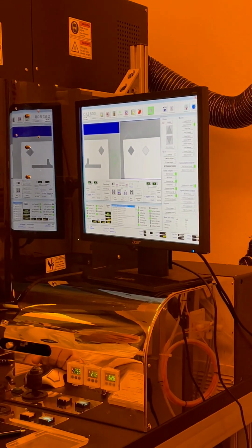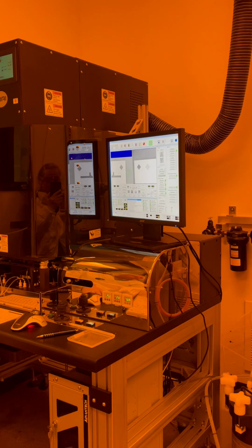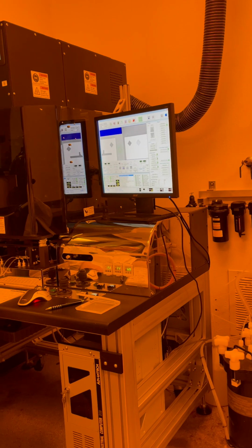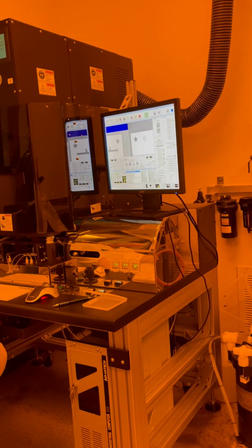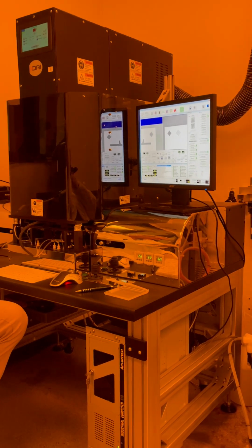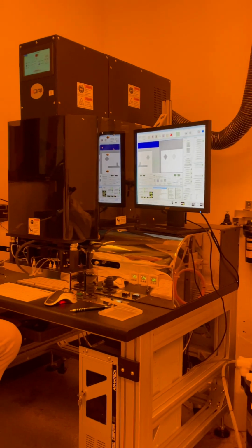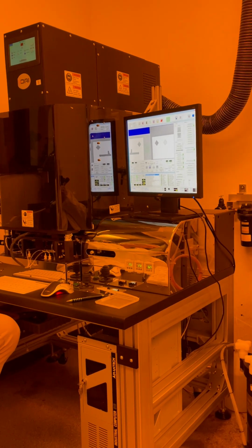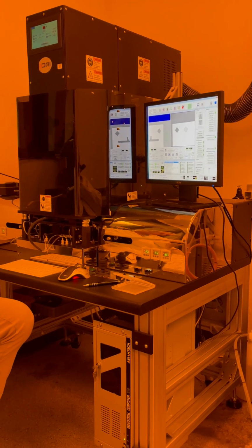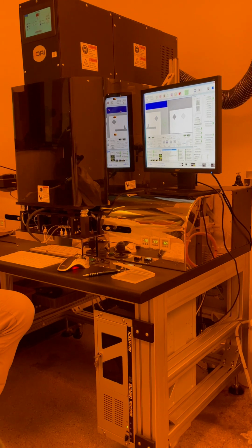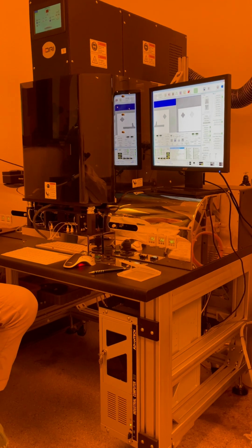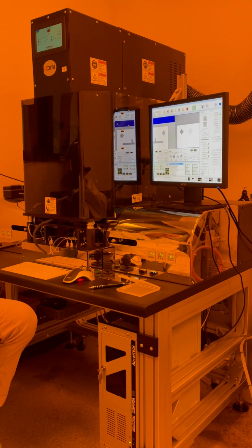Is your vacuum contact, so the chuck has a rubber seal. The rubber seal comes up and makes contact with the mask, and then we go into a soft contact and turn on the vacuum pressure. So it just kind of pulls them together. And then there's a hard contact mode as well, where that just blows nitrogen behind the wafer to press it up against the mask. Very straightforward.